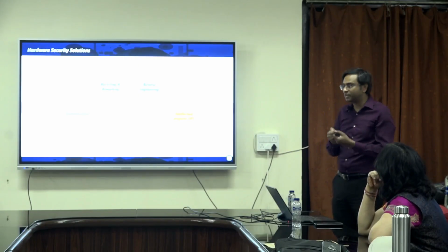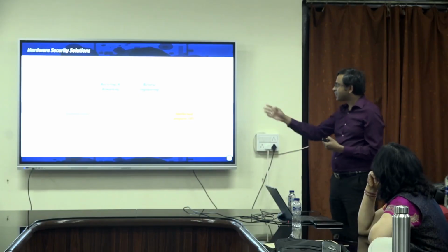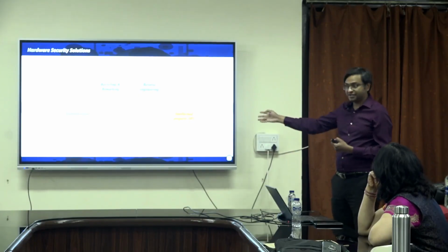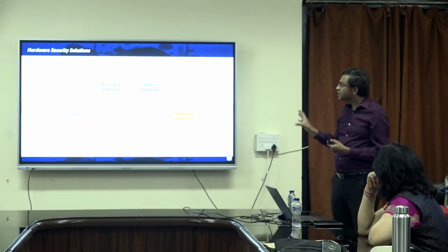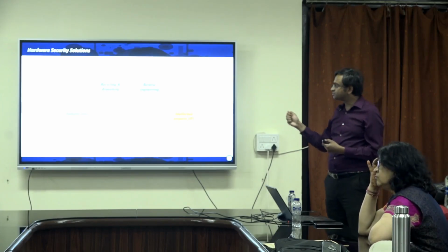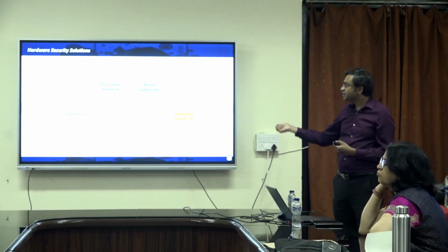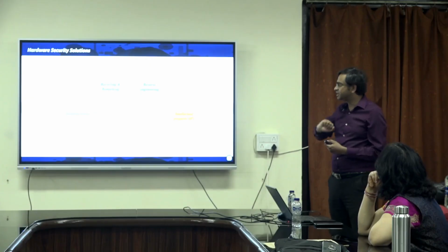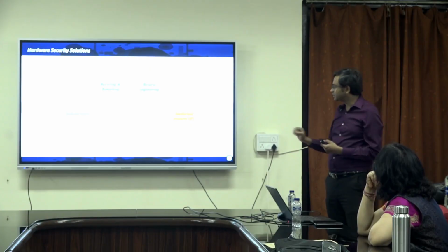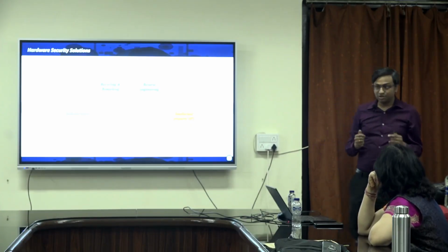So you kind of compromise on the performance of the chip. Reverse engineering, and then, as I told you, the intellectual property. These are the things that we wanted to see whether we can tackle using 2D material. I have written down the solutions, and I'm going to talk about this 2D physically unclonable function, anti-counterfeit solution, camouflaging, and the watermark, all using 2D material.